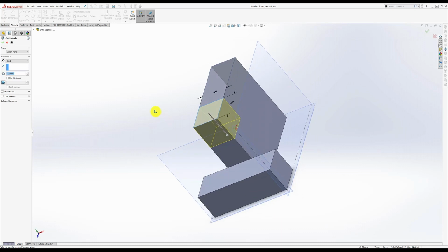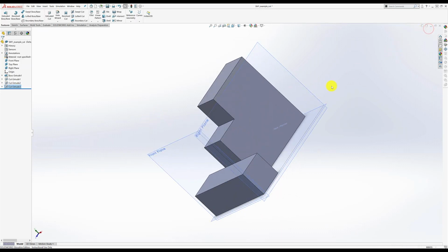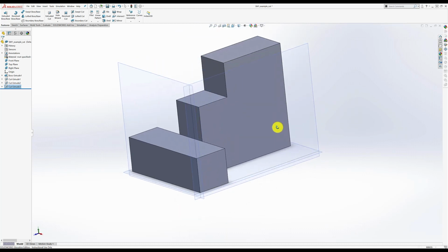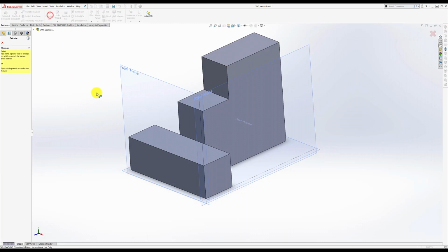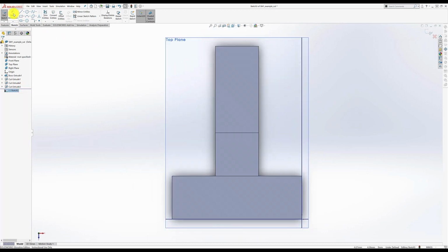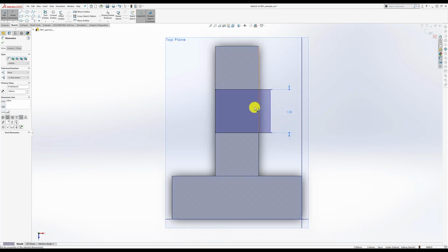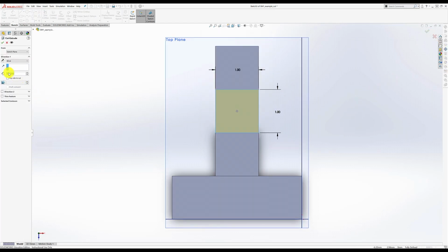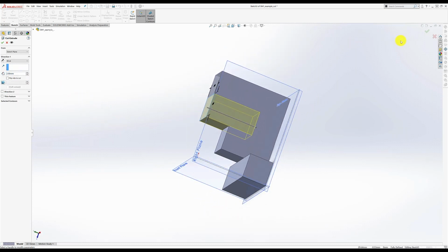And you can see the yellow preview showing up as to what it's going to be like. Great. Now I have just one more cut to do, and we'll be totally done with this. Okay, so extrude cut onto this surface. Look normal to that. And use my smart dimension to get that to be exactly the way that I want it to be. And I'm fully defined. And this one needs to go down, I think 2. Let's take a look. Yeah, that's right.